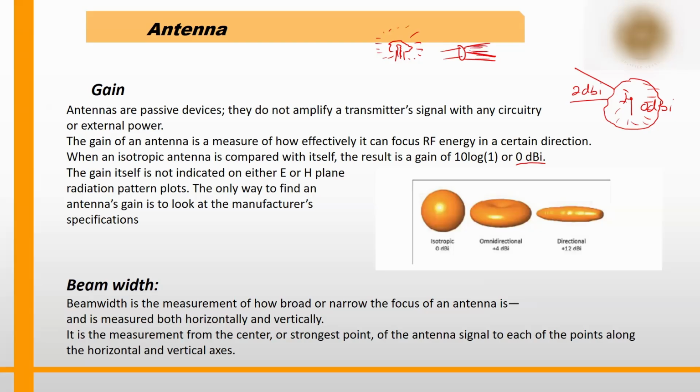If you change the lens, with a very good lens, it will concentrate at a single point. The energy that it is focusing is high at this point. In this example, the radiation is going everywhere, but here the light is getting focused on a particular place. So all that energy that was going everywhere is now focused. So there is a passive gain. That's what happens in the antenna also.